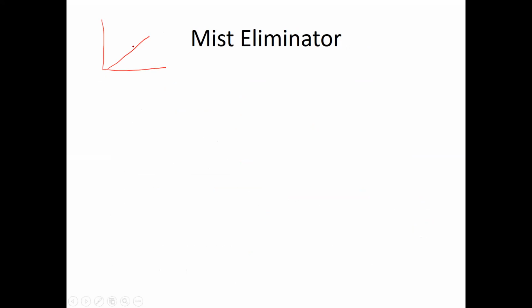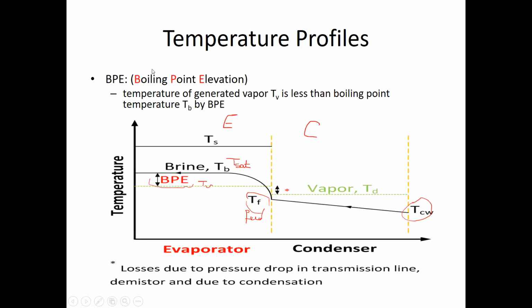You're right. And we have even talked about that in terms of desalination in general. For thermal desalination, we try to operate at lower pressure because at lower pressure, the saturation temperature is low.